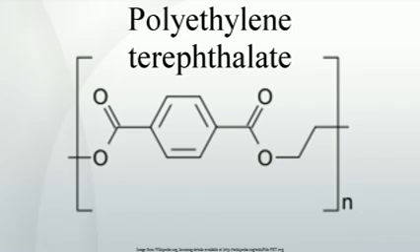Non-oriented PET sheet can be thermoformed to make packaging trays and blisters. If crystallizable PET is used, the trays can be used for frozen dinners, since they withstand both freezing and oven baking temperatures. As opposed to amorphous PET, which is transparent, crystallizable PET or CPET tends to be black in color. When filled with glass particles or fibers, it becomes significantly stiffer and more durable.